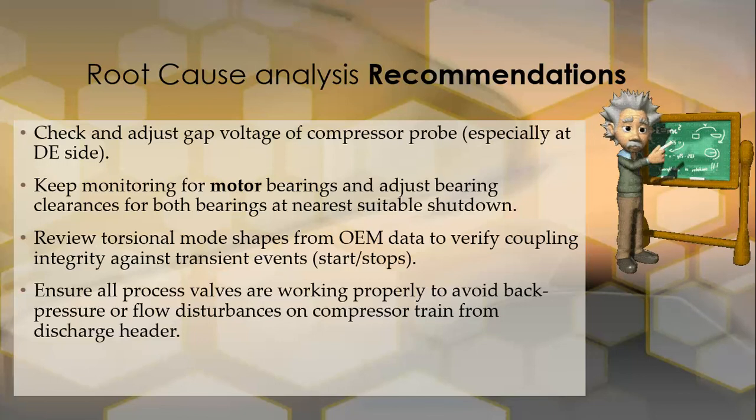Start-stops. As we mentioned before, there are multiple start-stops from the operation department, and they claim that there is no limitation on the number of start-stops per hour. Last but not least, we recommended to ensure all process valves are working properly to avoid back pressure or flow disturbance on compressor trains from discharge headers.